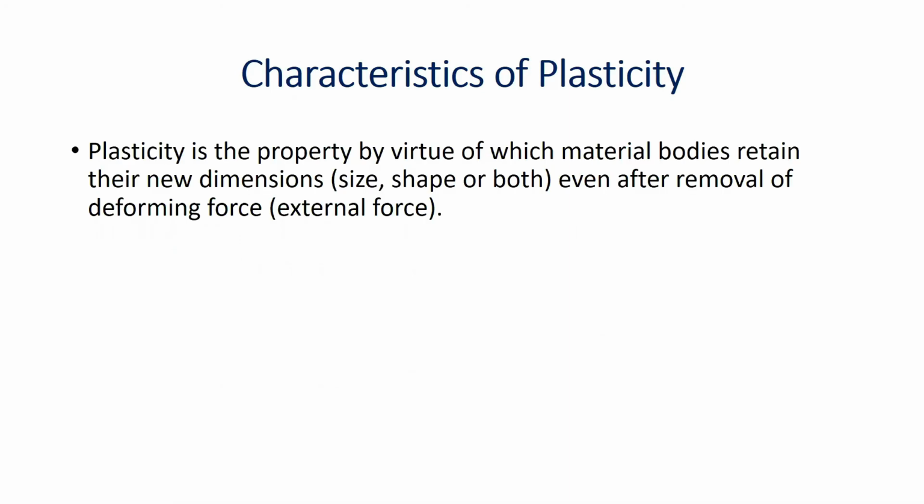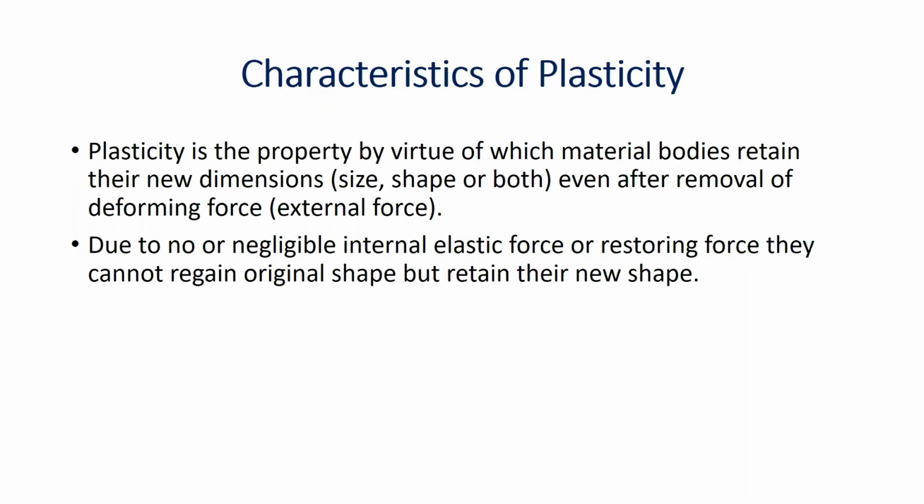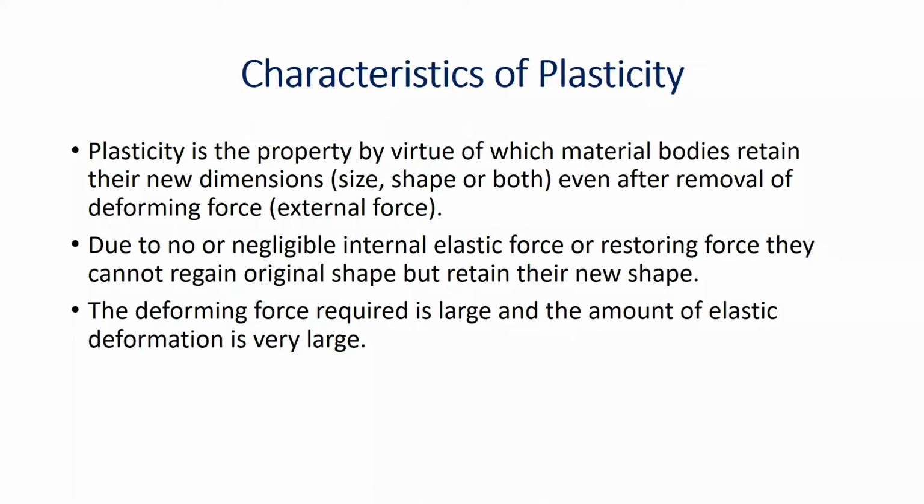Now, let us study the characteristics of plasticity. Plasticity is the property by virtue of which material bodies retain their new dimensions, size, shape, or both, even after removal of the deforming force. It is the defining character of a plastic body. When the body is stretched, the interatomic spacing increases, and when it is compressed, the interatomic spacing decreases. In both cases, internal restoring forces are created in the body, which tend to restore the atoms back to their original positions. Due to no or negligible internal elastic or restoring force, plastic bodies cannot regain their original shape but retain their new shape. In case of plastic bodies, the deforming force required is large and the amount of